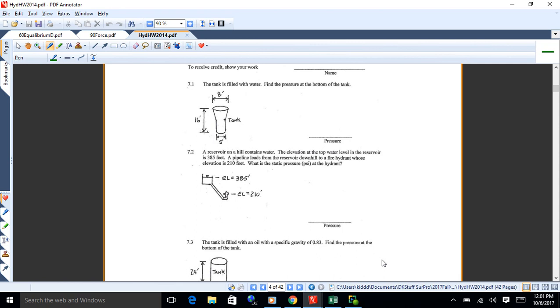This depth times 0.433 gets you pressure. That's it. And how the stuff's connected together, if it's connected at an angle, or if the container's an odd shape, or if the container's big, or if the container's small, doesn't make any difference. It's just depth goes to pressure. That's all there is to it. We're doing all right with that? Okay. So that goes for 1.